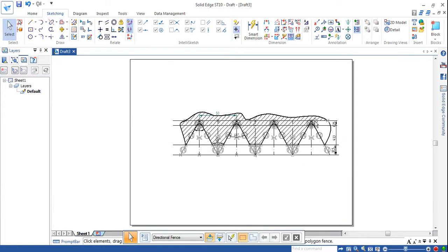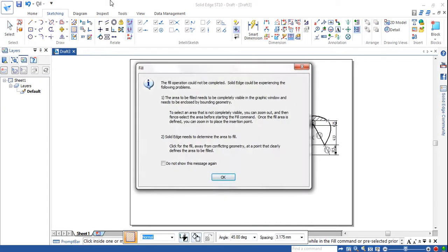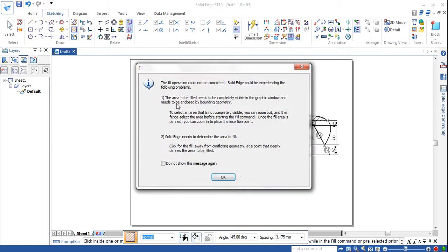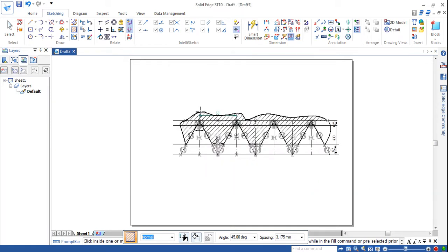Okay, fine. So guys, I forgot to dash these parts here. I'm going to do that now. Dash. So what is this dialog box? I've clicked on the outside part which is not enclosed. So I'm going to do that again. So this part is not enclosed now. If I click this here, it will show an error dialog box. So whenever you're doing dash, the boundary region should be a closed curve.